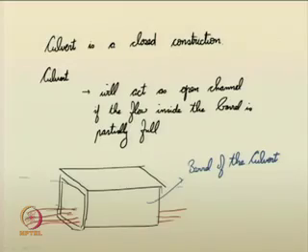If it is partially full, if the flow depth is only partly filling up to this height, and the flow is being maintained in the culvert, which is the case in many of the culverts. If you design many of the culverts, that is the better situation we require. Such flows are open channel flows, and you can use the open channel mechanisms to understand the culvert.